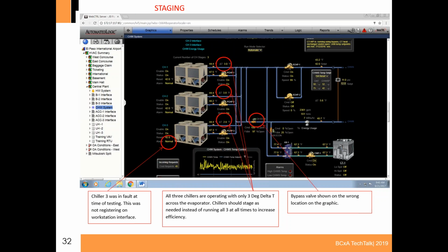The other thing is usually the storage is a moving window of data points. So if you do 1 hour, you could probably hold a week's worth of data, which is valuable. Whereas if you do 1 minute, you could only hold 1/60th of a week's worth of data. So it kind of depends what it is you're trending.